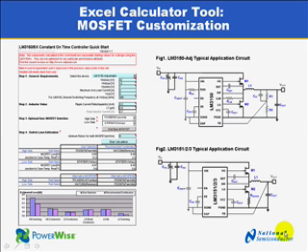The Excel tool for the FET selection offers you this view. You basically enter your data here into the blue fields and you can select a high side and a low side FET already. Then you go Start Calculation and the Excel tool will now calculate, showing the user selection, so what you selected, and it will show what the system recommends.